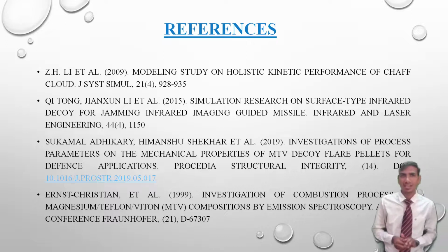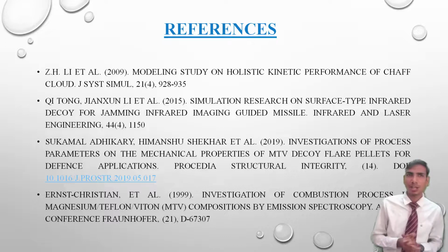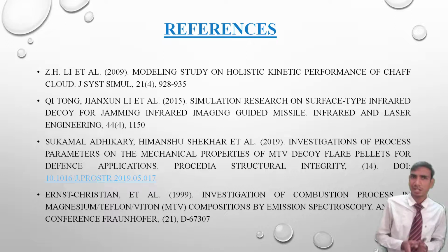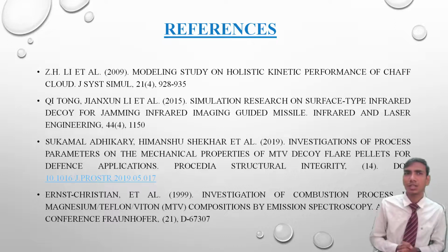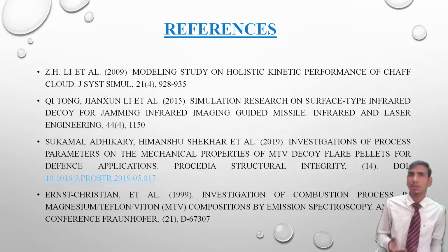Yes. Suppose the aircraft is approaching an area that is guarded by air defense. This towed decoy will help the aircraft to dodge the incoming missiles. Each and every Rafale of India has this decoy, with one decoy under each wing. So whenever the Spectra EW suite of the Rafale detects incoming missiles, that is SAM or air-to-air, these decoys are released. These decoys will lure the incoming attacking SAM or AAM missiles away from the protected platform by creating an attractive false target signal. The missile will divert from homing on the actual target, that is the parent aircraft.